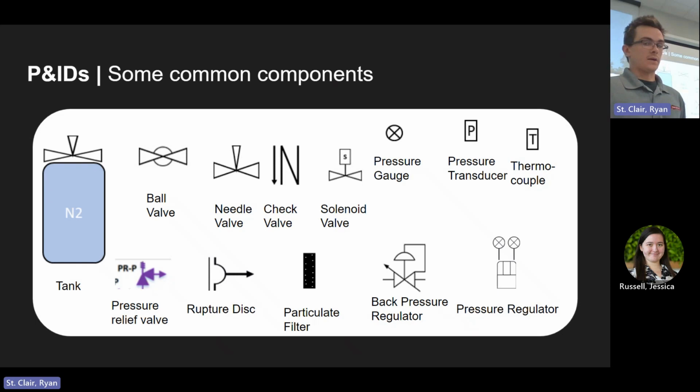And then you have a thermocouple. This is a temperature sensor, and there's different types. I'm not too familiar with the different types. There's K types and T types, but they all have their different attributes, different ranges. Important to note that with any of these sensors, there's always going to be some kind of sensor delay between what actually happened and when you read it. This is especially the case for a thermocouple where it's reading temperature, but it only reacts so fast because it only has so much time to actually heat up, and only so much time for that heat transfer process for the fluid you're trying to measure to transfer that heat to the thermocouple to get them to equal temperatures.